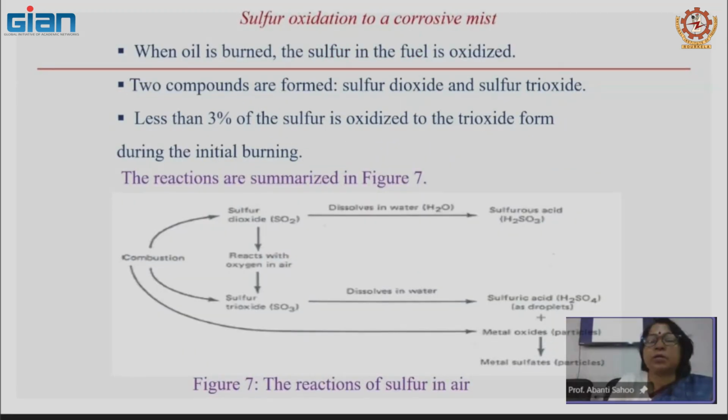We can convert it by carrying out the reactions in fluidized bed reactors and get sulfuric acid dissolved in water. Sulfur dioxide reacts with oxygen or air to form sulfur trioxide, which then dissolves in water. Or we can combust it, which will produce sulfur dioxide, or sulfur trioxide also. Both sulfur dioxide and sulfur trioxide we can absorb in water to produce sulfuric acid.